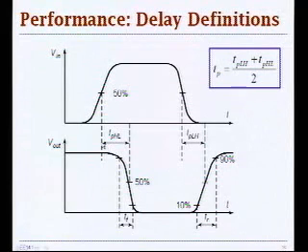And we defined 2 delay quantities, TPHL, which is the propagation delay when the output signal undergoes a falling transition, and we also defined TPLH, which is the propagation delay when the output undergoes a rising transition. And these 2 delays, which we defined relative to the output of a gate, have real physical meaning because you can really observe and measure them on your waveforms.